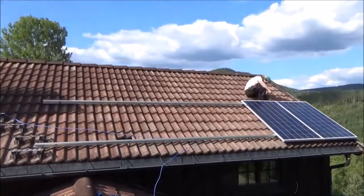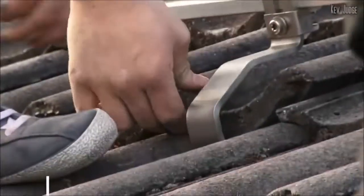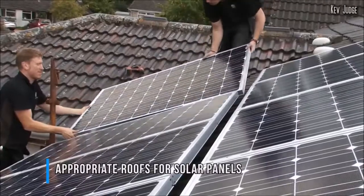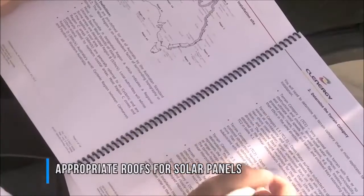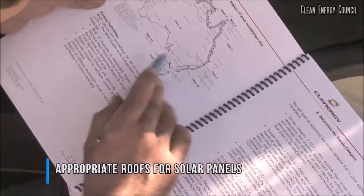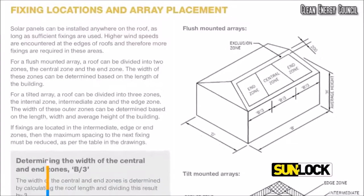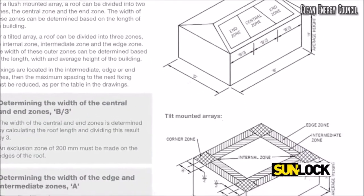The most important parameters that determine whether or not a roof is appropriate for a solar panel installation are its inclination and its orientation. Your solar energy provider can calculate exactly how much sunlight your roof will receive during the whole year. Although solar panels have a weight of only 2 to 4 pounds per square foot, structural safety is definitely another important factor.